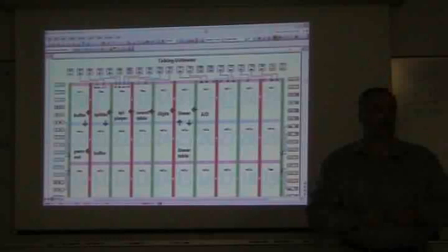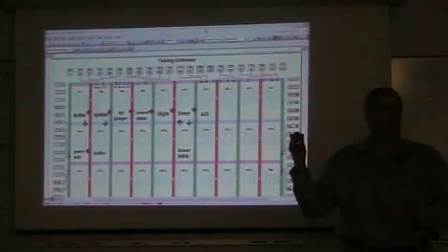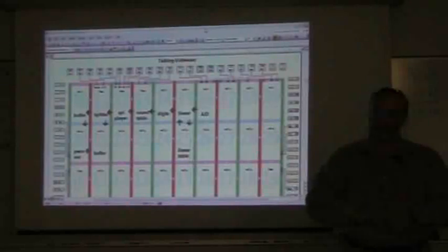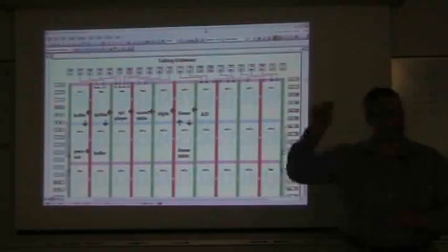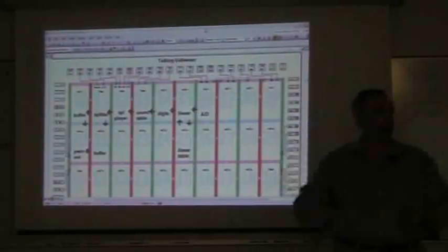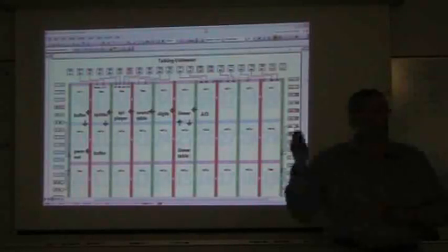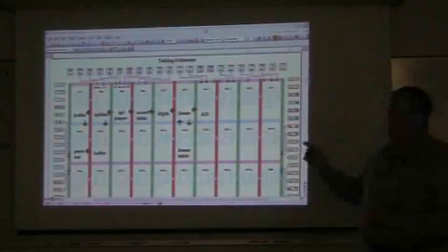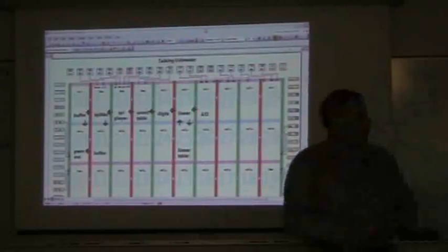And all I did in my output table was to have all of those values either be sync or blank, and it comes out cleanly sync or blank if it's below this level. Otherwise, you get a pixel level. And it makes a nice clean video output frame on the output, and it allows for trivial processing. And again, it's using this simple technique for A to D, D to A, and linearizing in software.